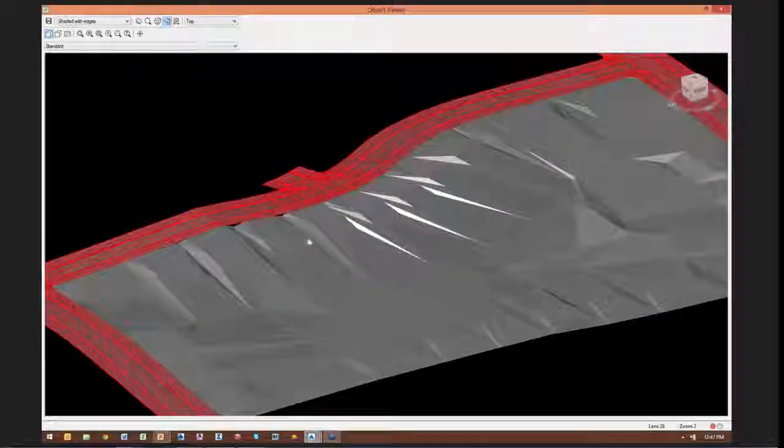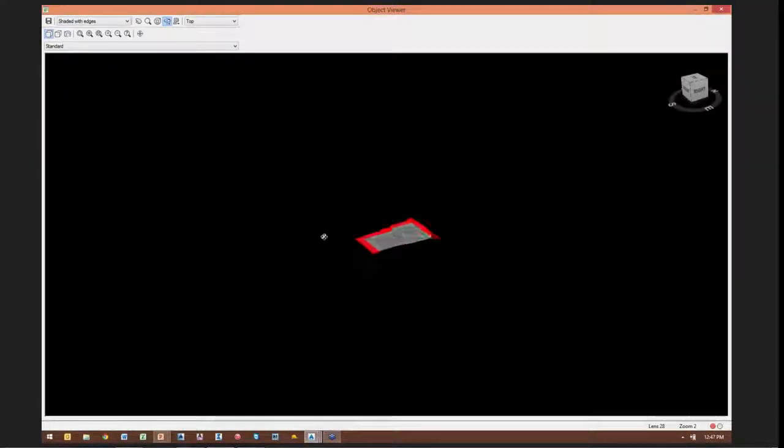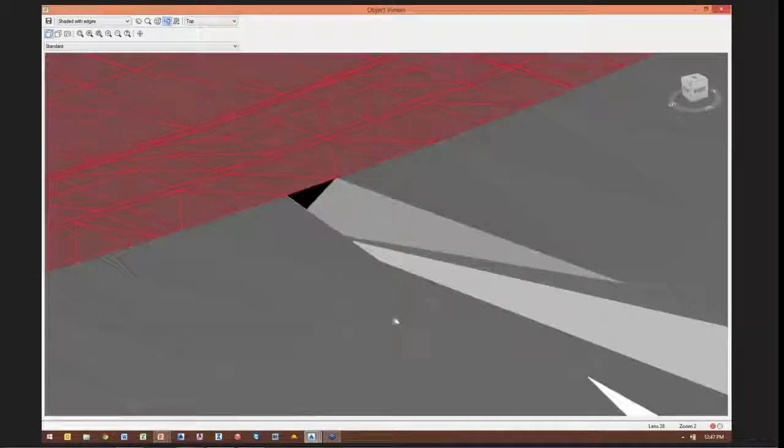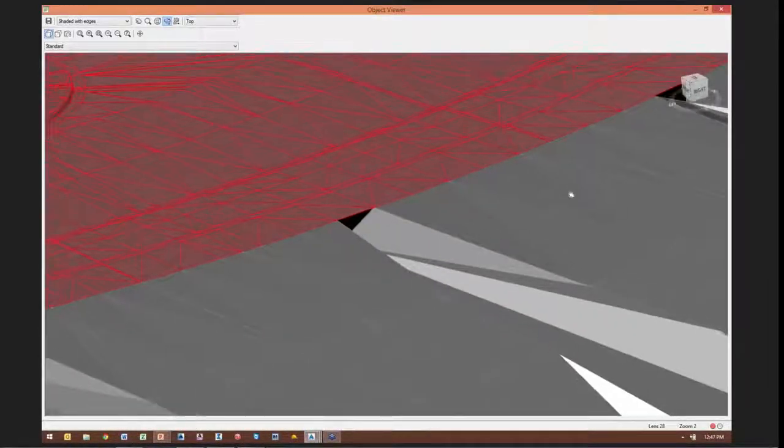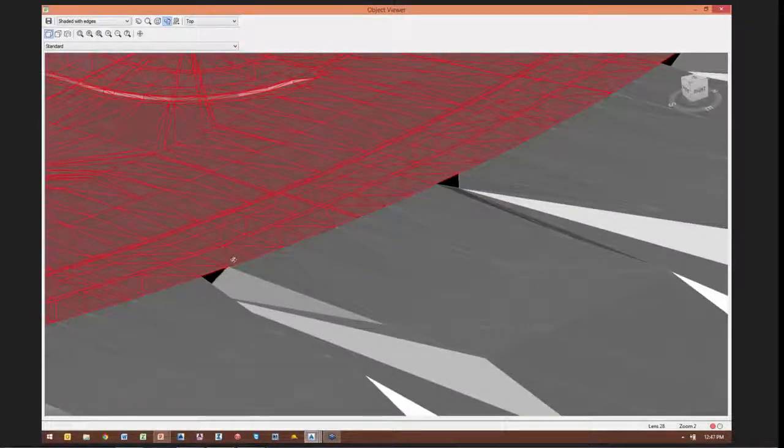Feature lines interact. If they're crossing and they're in the same site, they're supposed to assume the same elevation. Well, that's true, except it doesn't quite work the way you'd expect in this situation. So we assigned elevations along the right-of-way to the corridor surface, but those lot lines that come up here aren't necessarily connecting to vertices along that right-of-way feature line. So the lot lines are still sitting down low there.